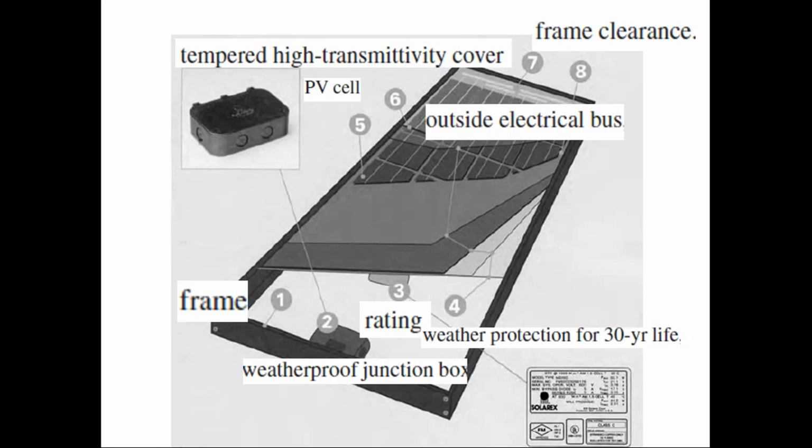From that you will be able to know the voltage rating of the module, the open circuit voltage, MPP voltage or rated voltage, short circuit current, MPP current or rated current of the module at standard test condition, and how much voltage it should withstand and in which tolerance band. That is to be incorporated on the back side of the module. It might be with the name of the manufacturer.